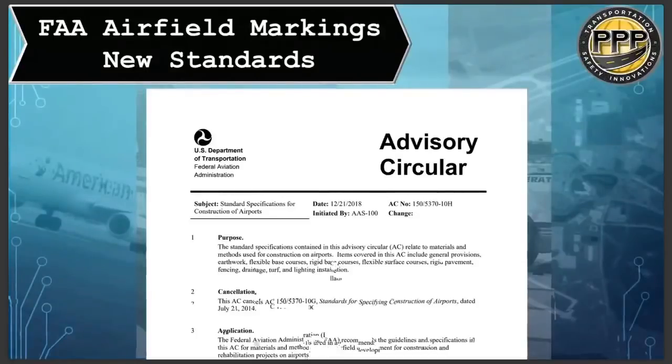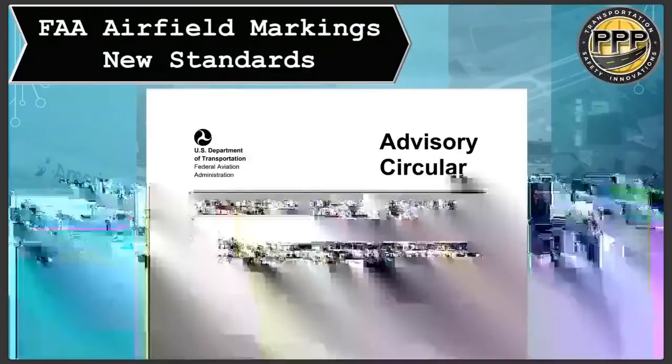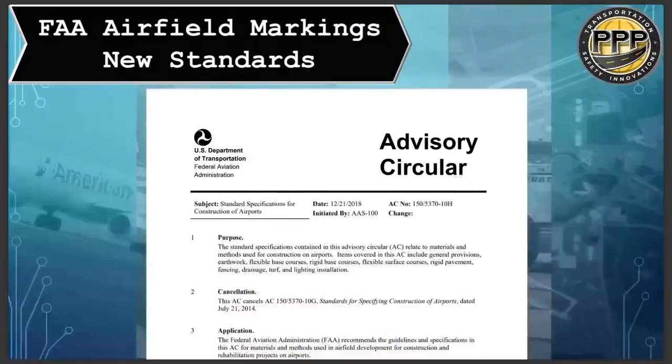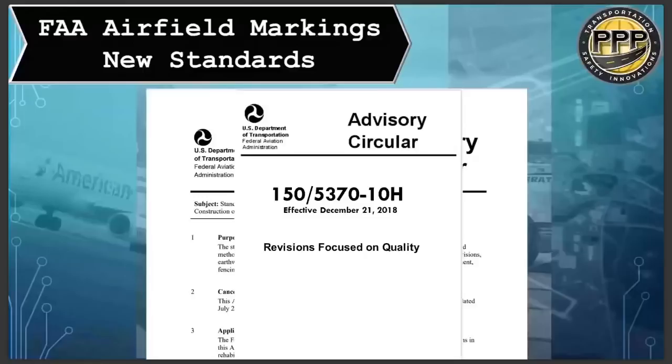The changes that we are referring to happened in December within the 5370-10. We'll take a real quick, brief overview of just the changes that affected airfield markings, and specifically the new maintenance criteria that has been defined for Part 139 airports.